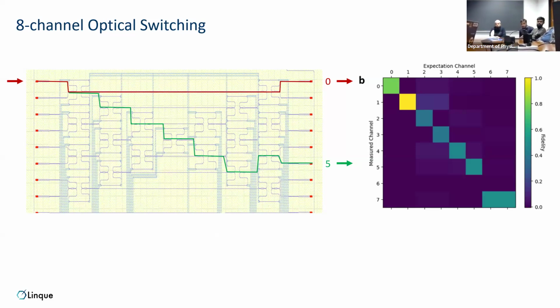What the graph means is that the rows are the target channel that you target, and the columns are all the photodiode outputs, or the other way around. The diagonal means you can tune the system so that the light goes to the output that you want. If it's off diagonal, then it goes to an output that you don't want. For example, in this bottom right half, one of the drivers for one of the MZIs was broken, so you couldn't tune that channel.